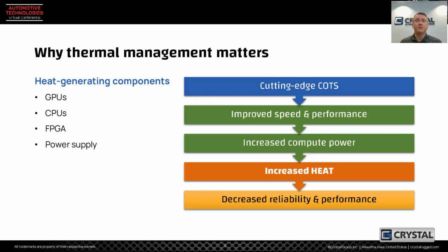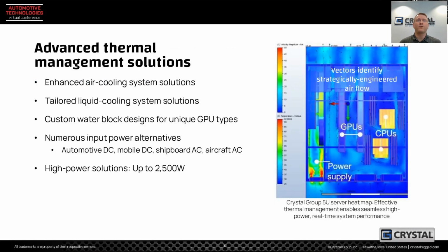Thermal management is also critical because electronics hate heat. Heat is the destroyer of electronics, and a very big kudos goes out to the design teams out there doing the hardware design on high temp components. That is very important, but it's a problem that needs to be solved from both ends. The higher temp components are important, and then also managing the heat, pulling it away from those components and dumping it outside the vehicle, not just in the cabin of the vehicle with the safety driver, or if you're up to level 5 with no other driver, you need to get the heat actually away from the parts and outside the vehicle.